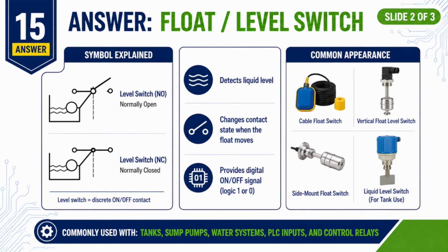It detects the liquid level and changes the state of its contact when the float moves. It usually gives a digital on-off signal, which the PLC reads as logic 1 or logic 0. Depending on the application, it can be normally open or normally closed.